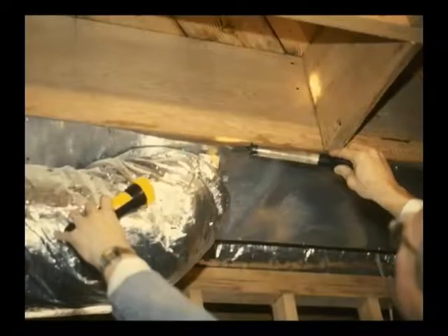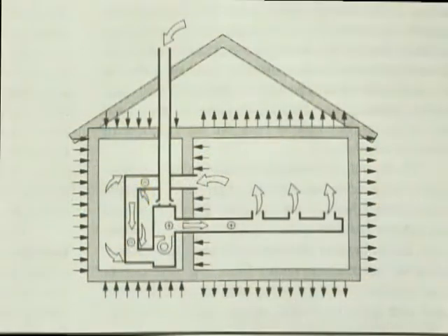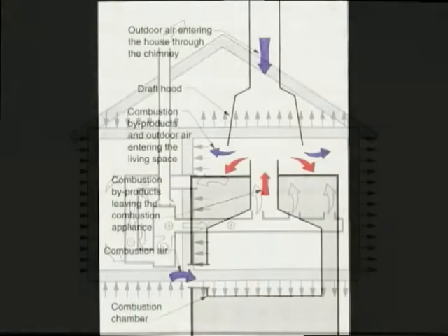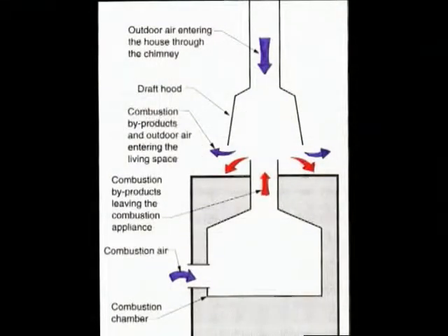Negative house pressures can be caused by many factors. Return duct leakage in an enclosed combustion appliance zone sucks air from that space. Any negative pressure in the combustion zone can weaken or reverse the draft in the venting system. Outside air can actually be drawn down the appliance vent to feed the return air leak, stopping the draft altogether.